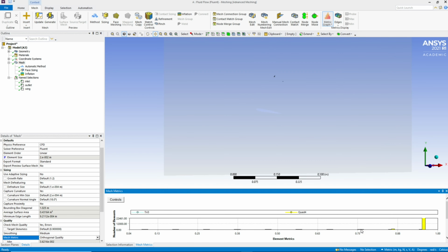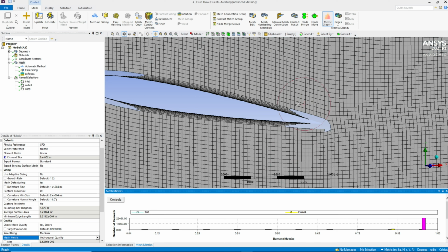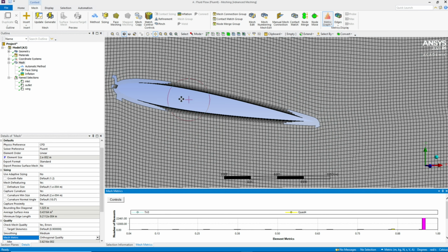We can select the ones that are more so, and even more importantly, we can look for the real sliver-like ones, and they're the boundary layer elements that are down here at the corner. Now, if we wanted to, we could fix those, and we could modify the mesh to reduce the skewness of them, but for the moment, we'll be content with this.